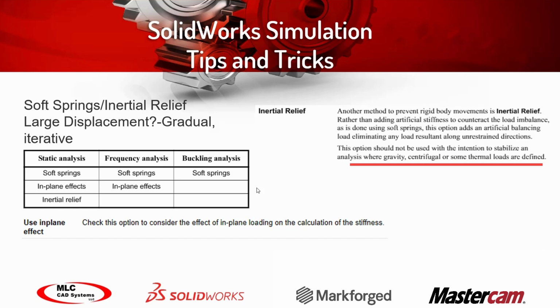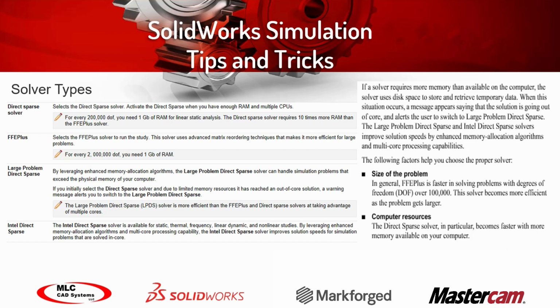But even if you don't have a self-supported load and you're trying to troubleshoot why your study won't solve or why it won't run, its mesh is fine, but it won't solve. If it's not the contacts, using contact visualization, it could be something to do with the loads or not enough fixtures. And you could turn soft springs or inertial relief on and troubleshoot your study that way.